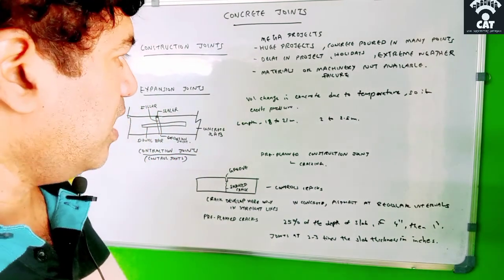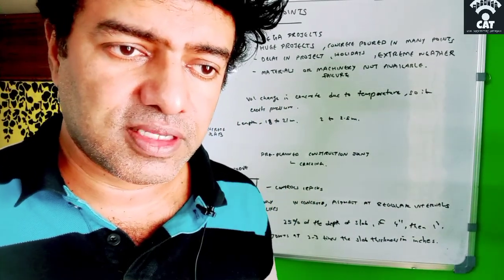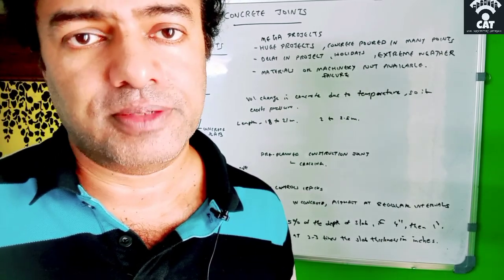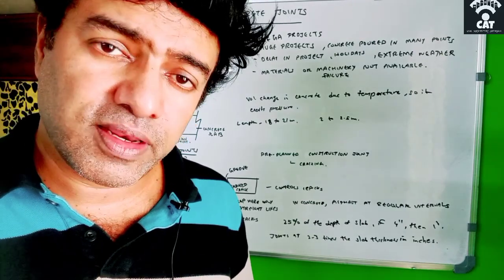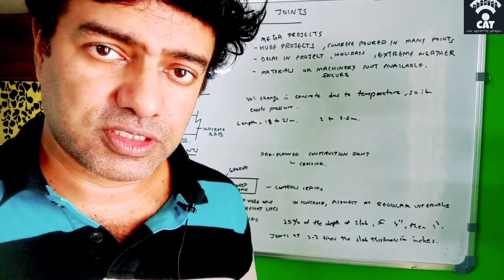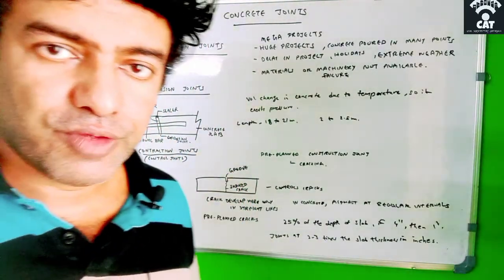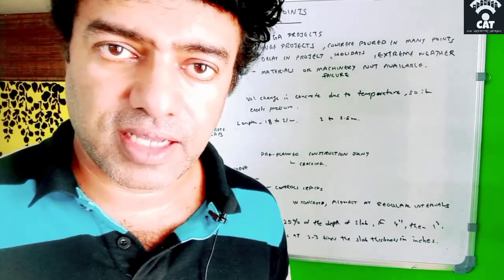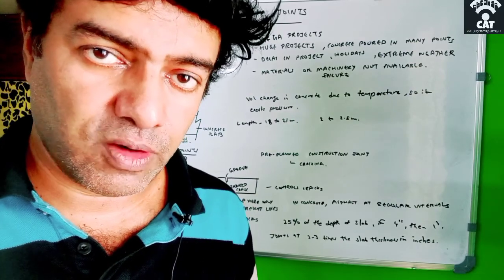It can be at some intervals or in a big slab. Let us say the example of a big mall: when the construction of a big mall is going on, the slabs we have to cast will be of very high length. So we usually provide this expansion joint at 18 to 21 meter intervals, or sometimes, if the case arises, at 2.5 meter intervals also.